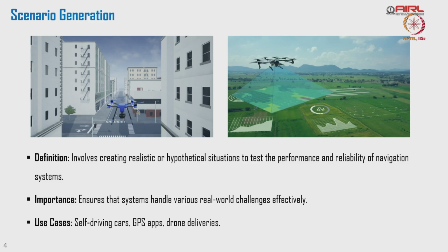So you need to create that scenario and check whether your global path planning algorithm or local path planning algorithm is able to provide the necessary control, and whether the inner loop we talked about, the flight control, is able to make sure the drone is stable while following the command. Suddenly you are expecting the drone to turn 90 degrees. The rate at which it is turning left or right is going to be a bigger challenge. How much acceleration can I have? What is the saturation limit? All this we need to verify before we really deploy.